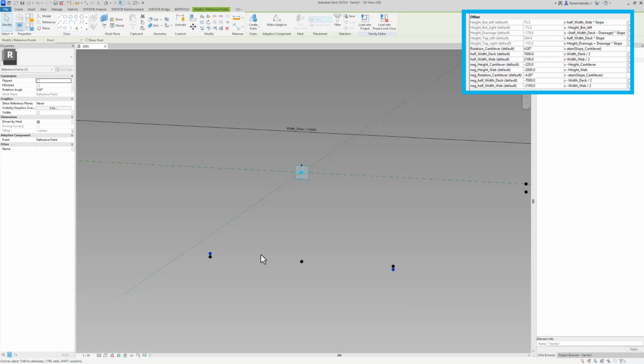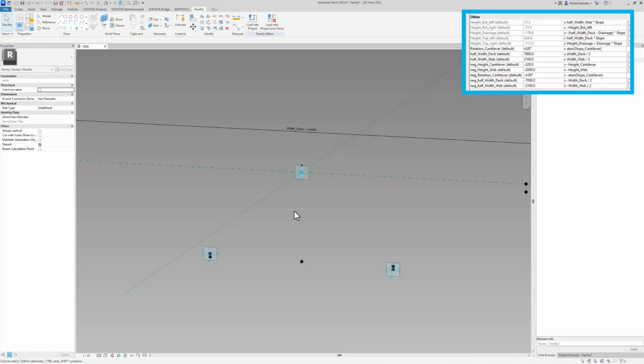And what I want to do, and to clearly show it, I will activate the reference planes because I want to now use reference lines to create the intersection of a 60-degree angle here. Because this is usually a task which would require a lot of calculation via formulas to get the proper horizontal and vertical reference points.